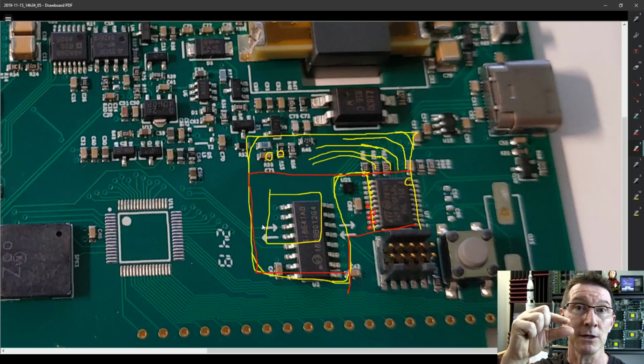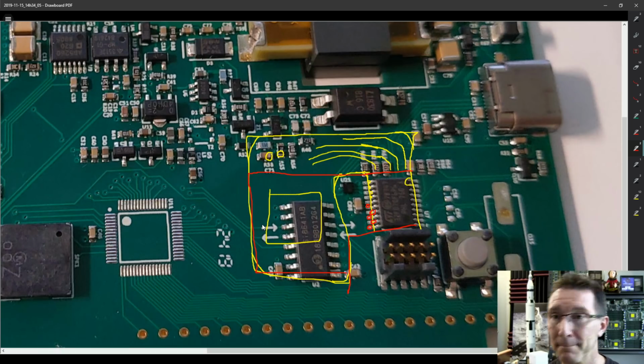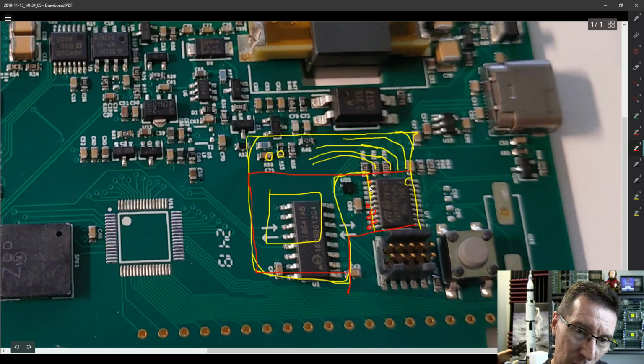So if the material is, you know, 0.5 millimeter, the bend radius, you want at least 5 millimeters. That's just a rule of thumb. So I think with the pin pitch, we're probably going to have trouble with the castellations on here. I don't like our chances of getting castellations with 0.5 millimeter pin pitch on a flex. I've never actually tried it at that pitch before, so I don't know.